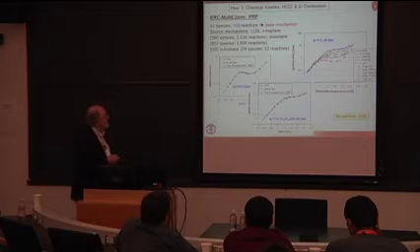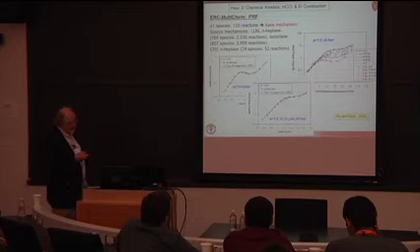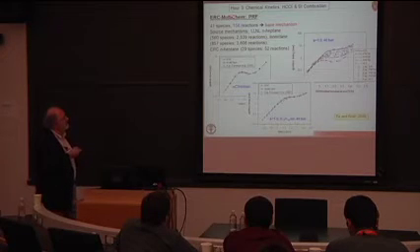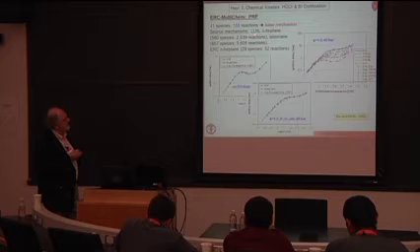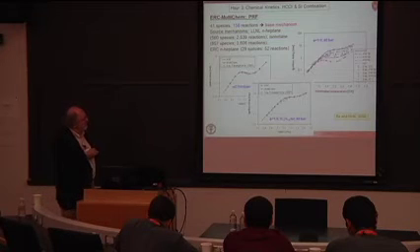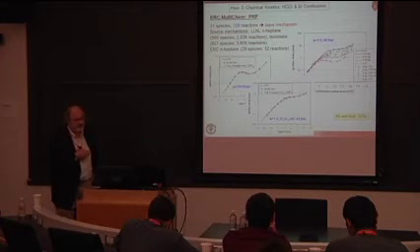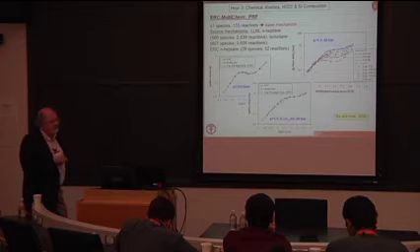So here you see that applied, for instance, in what we call the Engine Research Center multi-chem primary reference fuel mechanism for N-heptane and isooctane. We started from the Lawrence Livermore N-heptane, 560 species, 857 species isooctane, and the ERC N-heptane mechanism, and combined all of this together to produce a 41 species mechanism for PRF.